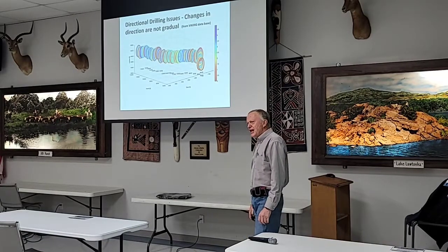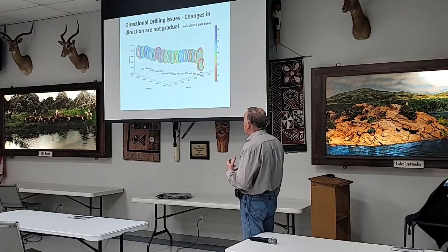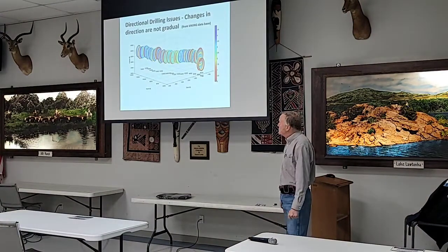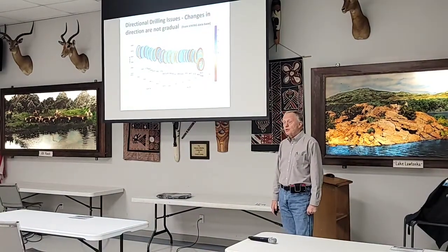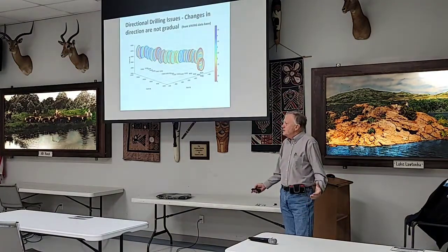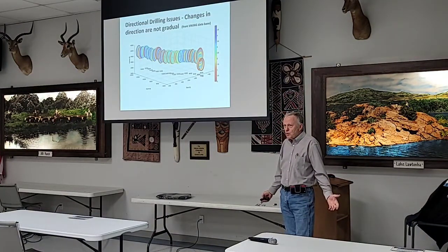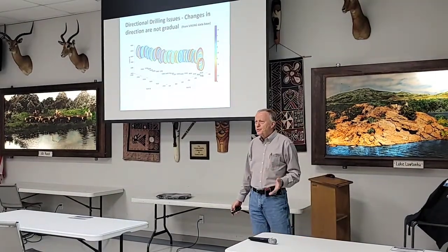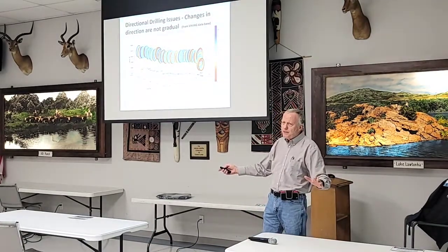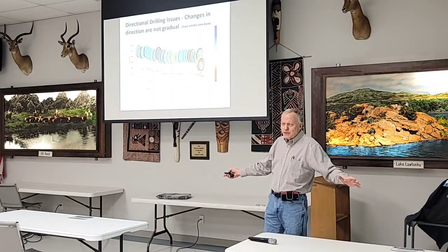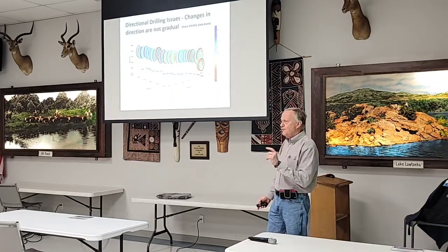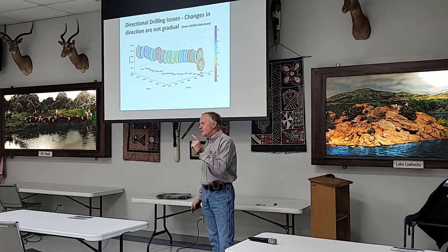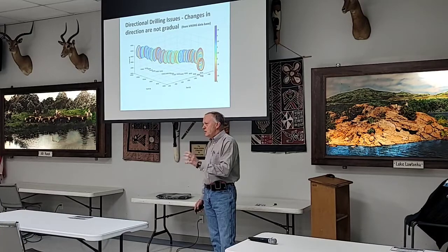This is an actual recreation with a finger caliper of what a directional drilling looked like when someone made just a little bit too much correction or hit a ledge or some kind of a problem down in the wellbore. When you've got something like that, if you could find that beforehand, you can run a string mill through there or some other way to clean that up. You virtually eliminate the problems. But if it buckles in that area, if you have distortion in that area, and then cycle it, that's where your deformation is likely going to be, and we tracked that back.